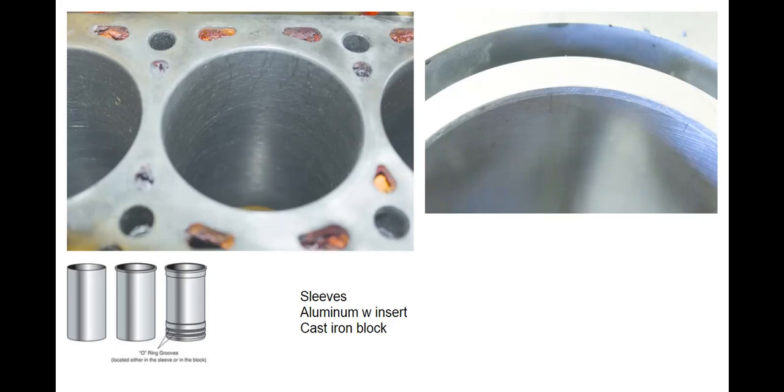This is handy for, let's say, an engine inside of a giant boat or a ship. The engines in a ship are usually so large that you can't really remove them from the ship, so you have to replace the components. You might have to replace a cylinder that's 4 feet long and 2.5 feet around, and this is how they do it, with these giant replaceable sleeves.